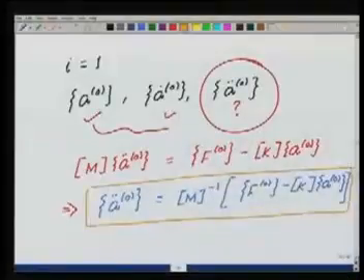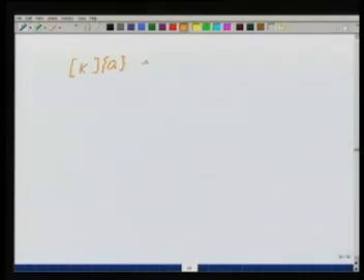Okay. Now remember that the time step size has to be small enough to resolve the temporal behavior of the solution. So imagine I am talking of a free vibration problem, I do not do the separation of variable solution. I use the direct approach, that is, I want to solve Ka plus m a double dot is equal to 0. Okay.